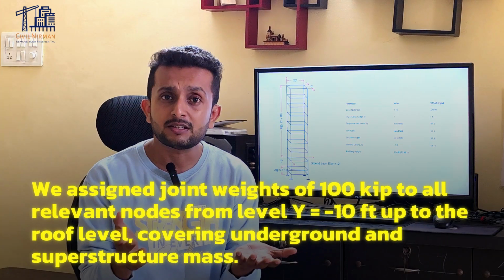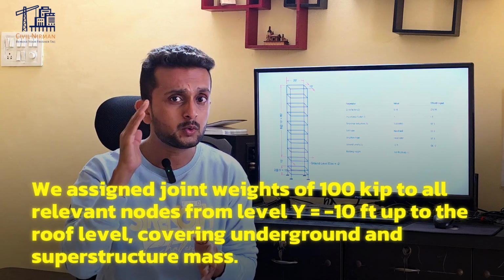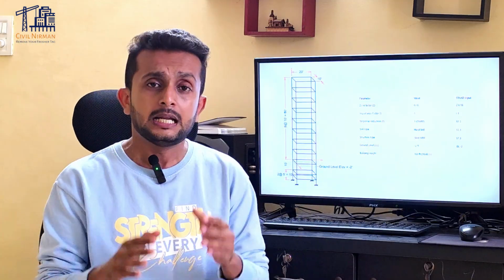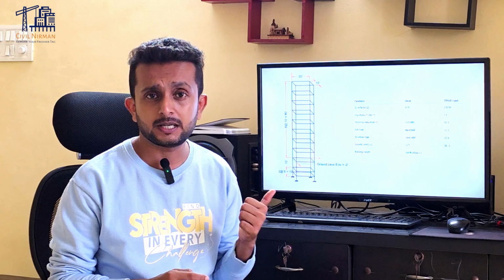So basically we have assigned a joint weight of 100 kilopascal to all the relevant nodes from level minus 10 feet up to the roof level, covering underground and superstructure mass. To represent how this will look in the STAAD editor, you can check this particular syntax. Further, I'll show you how I have modeled this particular sample problem in STAAD. But to give you the overall introduction summary, here I have specified this.